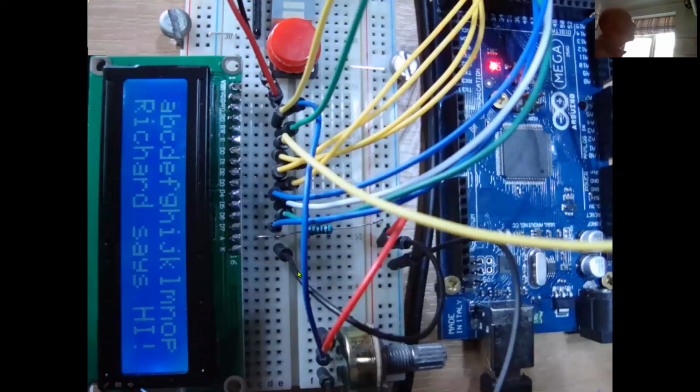Well, yeah, here is a picture of my one that I use. Okay, so it's on my breadboard, which is screwed to the board so it can't move. So here is the wiring. What I've done to simplify things on my one, I've used the data, these 4 yellow and these 4 other ones here. There's data 0 to data 7, and these all go to port A, which is over there on the end. Okay.